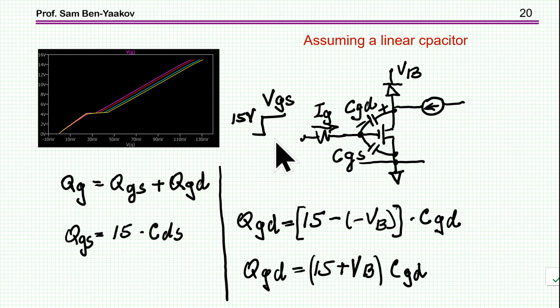So now we feed in a signal. There is a current through the resistor, and this voltage at the gate is starting to rise until it reaches the threshold of the transistor. And then the transistor starts to conduct. Nothing really happens until the current gets to the current of this source, and then the current of the diode drops to zero, and the voltage starts to go down.